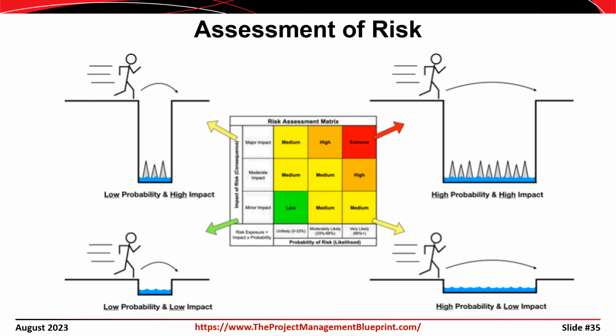So you can consider both of these variables when you consider the assessment of risk in a structural engineering context as well. Think about what happens if a beam fails, for example. That might lead to the collapse of one floor, or that might lead to the collapse of a bay of framing or something like that. Whereas if a column fails, that could lead to a progressive collapse and bring down a building. So we consider assessment of risk in structures kind of like that as well.